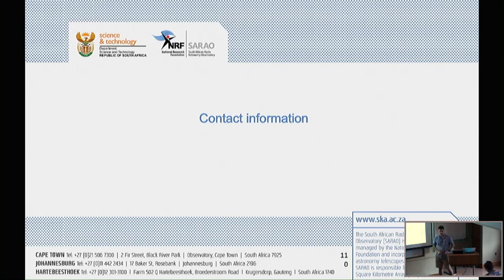Question? You spoke of the need for keep-alive packets. Does the Casper firmware do that? So there's a process that runs around to populate that ARP table. It sends out packets basically saying, hey, who's got this IP address? And each one of those that goes out allows the switch to learn its MAC address. And those go out, I think, every 100 milliseconds or so. Is Robin here? What's the rate for our packets? 10 a second. Yeah, 10 a second.